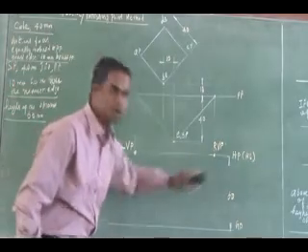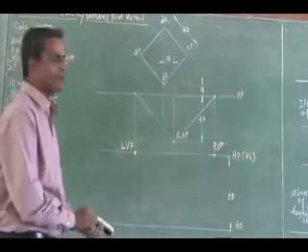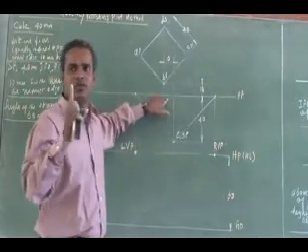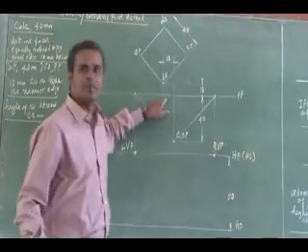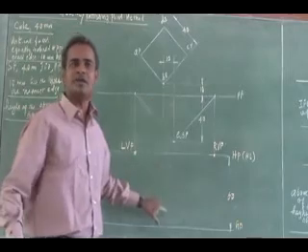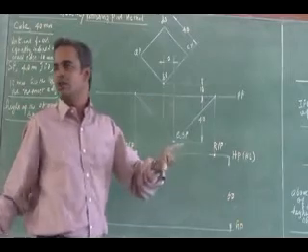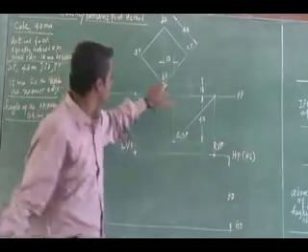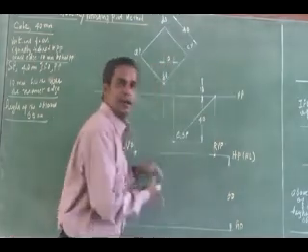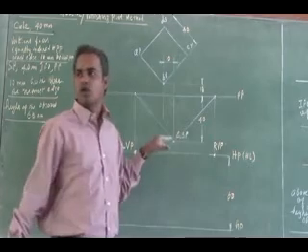So you don't have the front view. What do I have to do? You know one thing: if an edge is touching the picture plane, listen all of you, what will I obtain in my perspective? The same length I will obtain in my perspective. Do you agree with that, right? If an edge is touching the picture plane, the same length will be obtained in my perspective. That is the concept I am going to use.